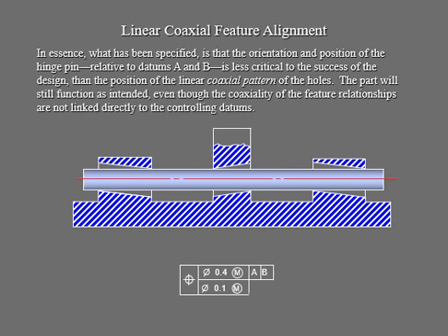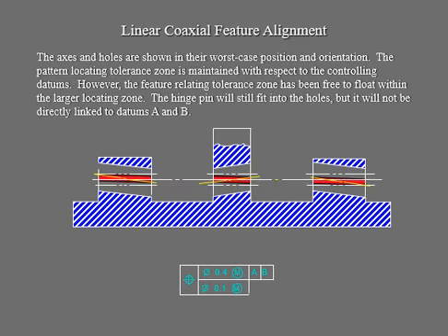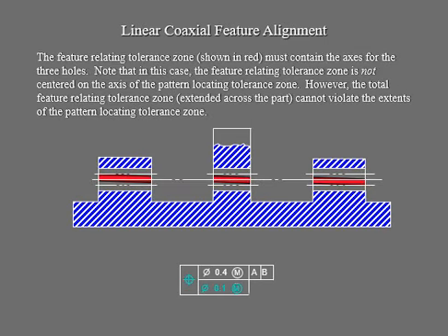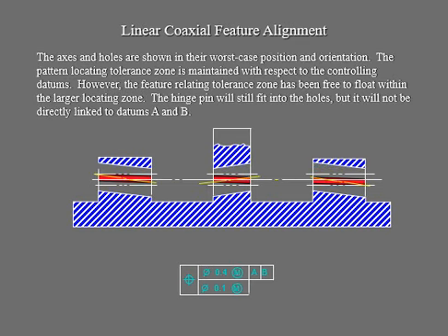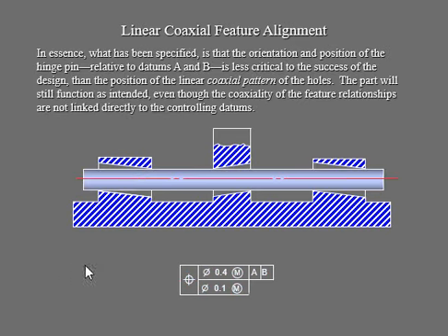Okay, and so right now we're putting in maximum material, meaning we want to leave the most possible material on the part. So your hole has to be as small as possible, and your shaft has to be as big as possible.